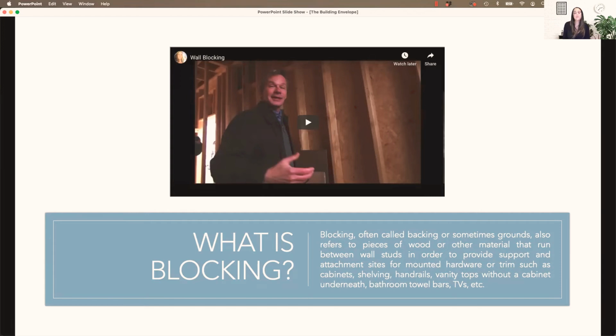If you can't connect to a stud wall, you can add what's called blocking into the wall. Now, this is something that as a designer, you want to prepare for and include in your drawing documents. So anywhere that you're going to be hanging something that's heavier, that may or may not hit a stud, you want to specify for blocking to be added into the wall.